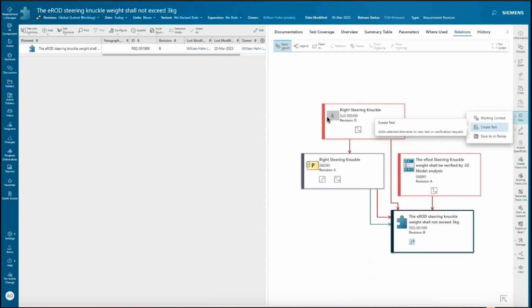If I've got a CAD model, great, I can mesh it and do some simulation on it. If I don't have a CAD model, if it's very early in concept design, AIMSim is really easy to toss some components together, run some basic simulations and say, hey, this design that we want, it's not even possible, right? Let's not waste the money to go build a CAD model when we know there's no possible combination, the hydraulics or whatever it is just doesn't work. So you get to those answers much quicker with a system simulation tool.